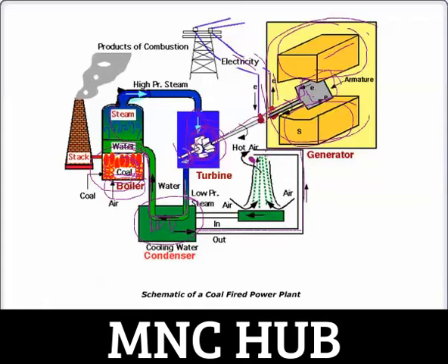So this is simply like a shower head. Almost hundreds and thousands of shower heads at the top of an almost 10-story tall building. And when these droplets fall down, the air that is going around these small droplets picks up the energy from them, and hot air goes out and cold water comes down.